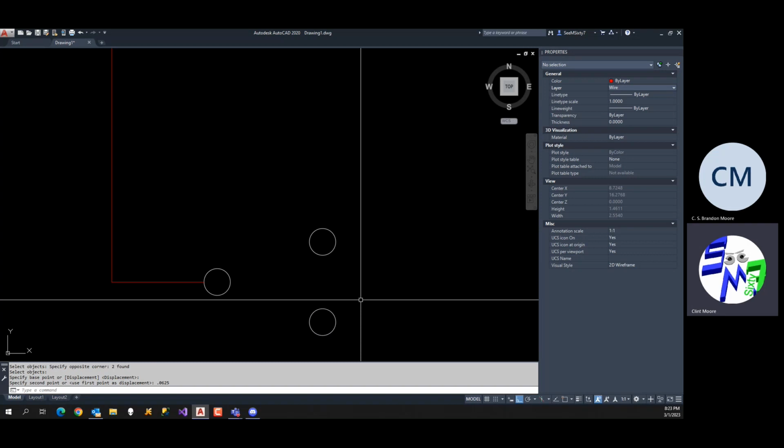And typically when people are working in the field, they have a tape measure and it has these units of measure on them. They don't typically have tenths of an inch or 74 32nds of an inch, that's a horrible number, but they don't typically have those things on their tape measure. So if you ever look at a tape measure, you'll typically see them go down to a 1/16 of an inch. Sometimes you'll see some that just go to 1/8 of an inch, but 1/16 of an inch is getting kind of small.